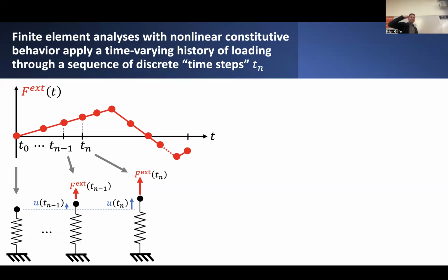The nice thing about this incremental loading approach to running a finite element problem, taking the load, breaking it up into load steps, and applying them incrementally, is that it also enables you to do some interesting things. You don't just have to load up the structure monotonically, ramping up that load linearly. You could also subject the structure to cycles of loading. So take the load, increase it, maybe then decrease it, and then maybe reverse the direction of the loads. That can happen in a lot of different practical scenarios where you might be interested in how the structure behaves under these kinds of cyclic loading deformations, as might occur during, let's say, an earthquake, where the structure isn't necessarily subjected to one instantaneous load. It's subjected to perhaps several cycles of loading, which can influence the overall behavior.